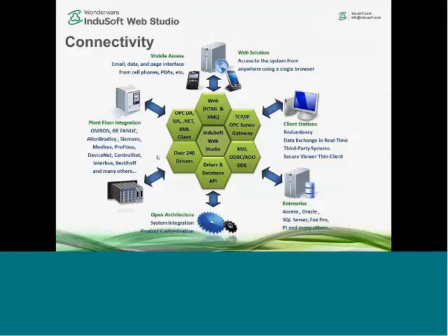And this really allows the flexibility to communicate between different equipment that has to connect together, that has maybe come into your plant over the years, dissimilar PLCs, and be able to get that information from one to the other. Also, it's not going to be uncommon to find equipment on machines, or connect to older machines, that are maybe serial devices. We've been writing these drivers for a long time, and we have RS-232 drivers, RS-485 drivers, serial, as well as dedicated cards, things like DeviceNet and CAN bus and things of that nature.